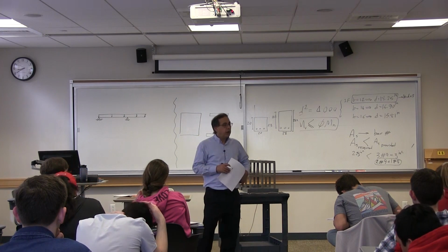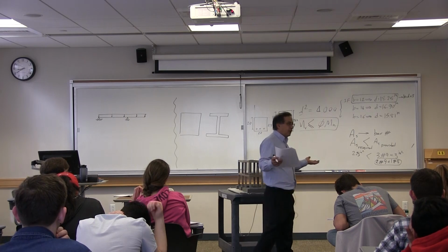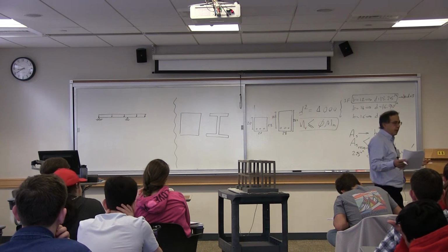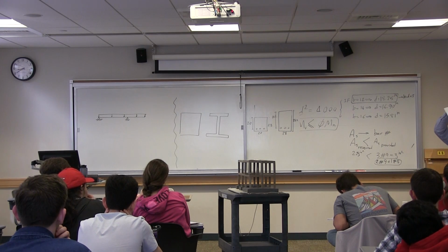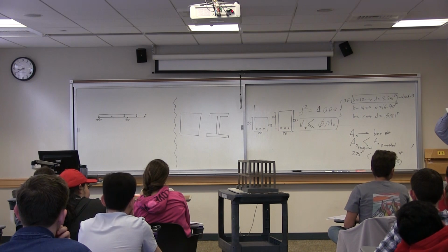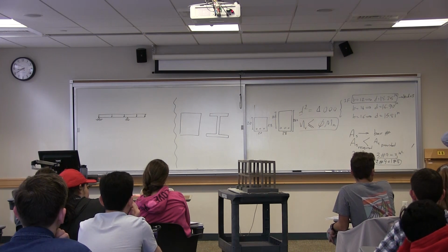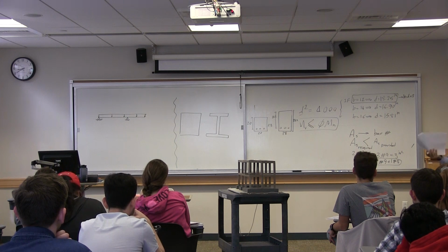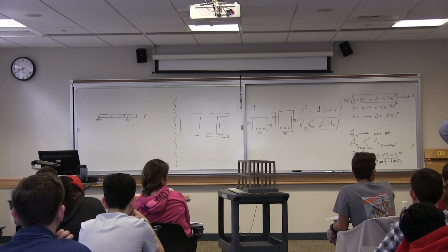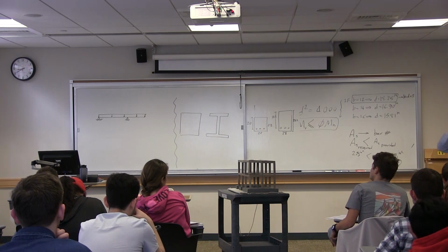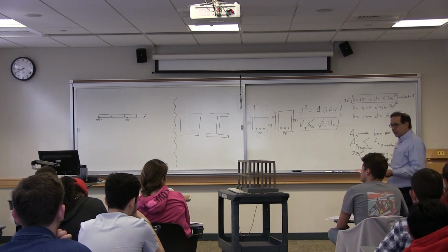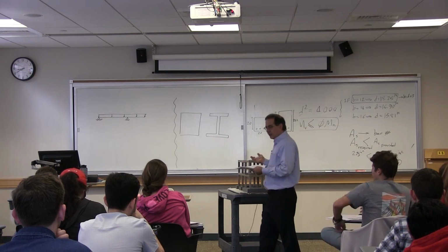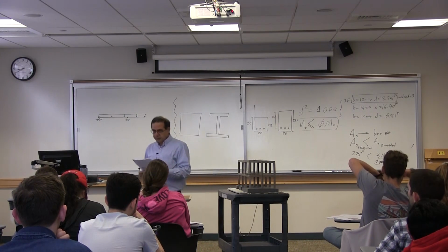They might have different locations. I mean, if they are at different locations, why should they be the same bars? If one is top and one is bottom, and if the moments are equal, there is no requirement to have any link between what the top bars are and what the bottom bars are. So, therefore, you would design for positive moment and negative moment.